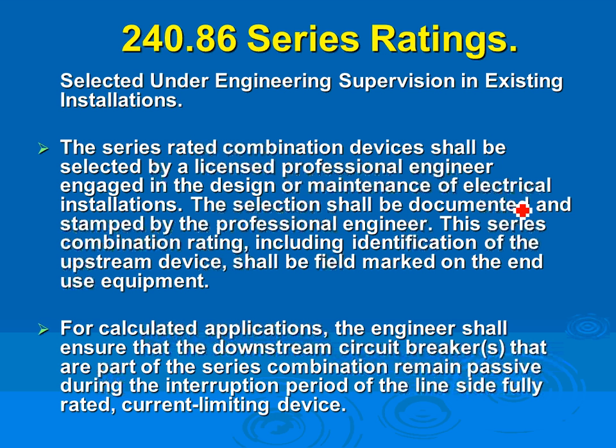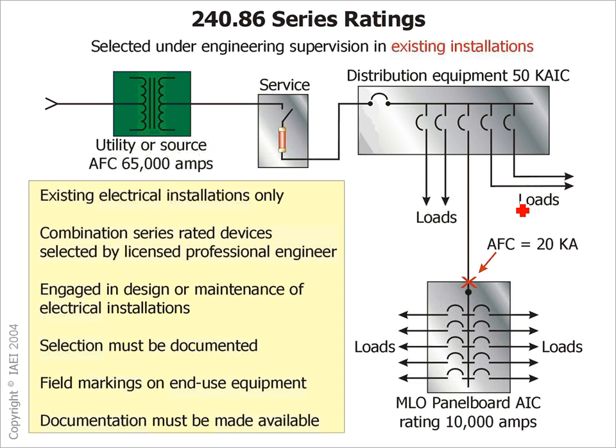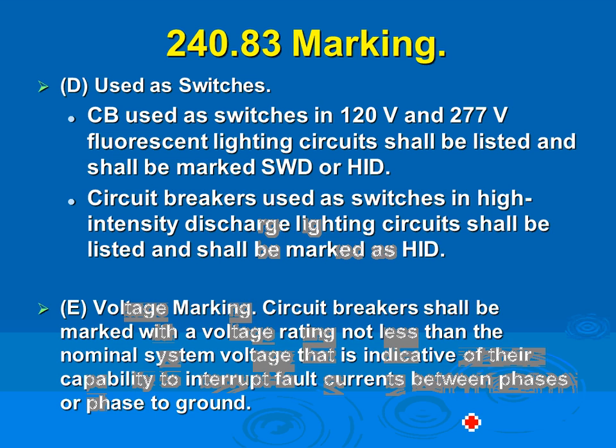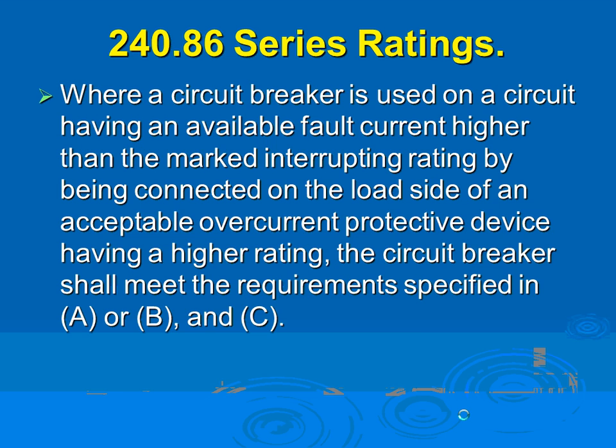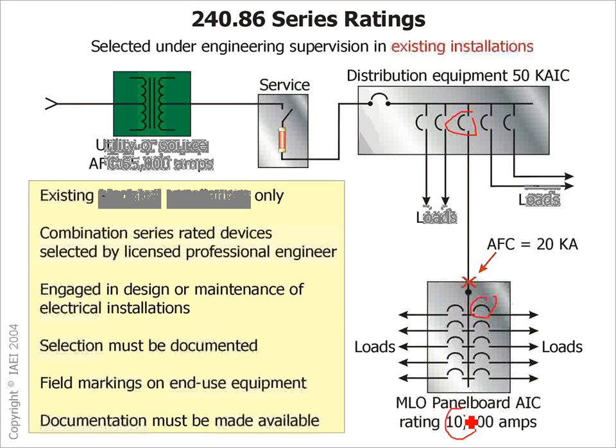So a licensed engineer can do that, or you can do it in the field. Here's an example, guys, of series rated equipment. These circuit breakers are series rated, so if there's any short circuit higher than what they're rated for, which is 10 right here, that big boy will take care of it.